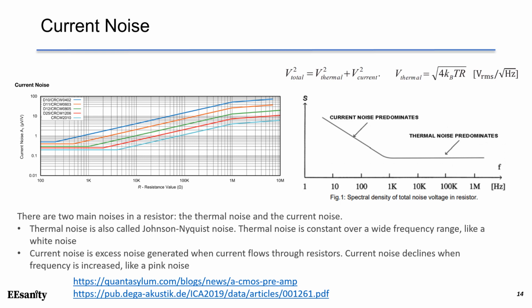Current noise is a relative noise voltage on the terminals of a fixed resistor caused by the DC current through the resistor. As you can see in the graph, it is expressed in microvolt RMS voltage per volt DC. You may want to pay attention to this graph when you are working on precise and low noise circuits, when the measurements are only a few microvolts.